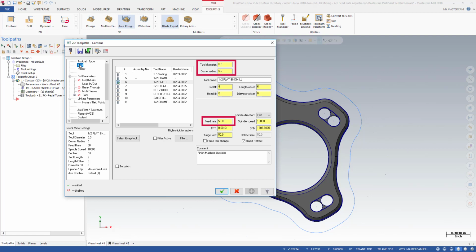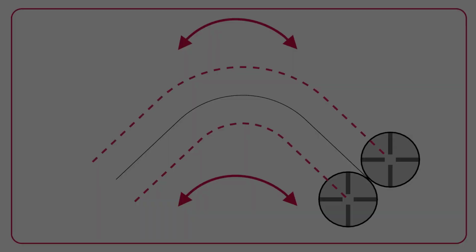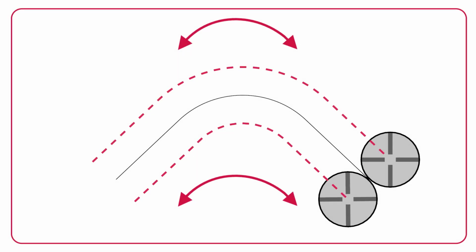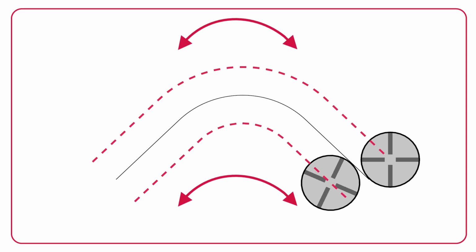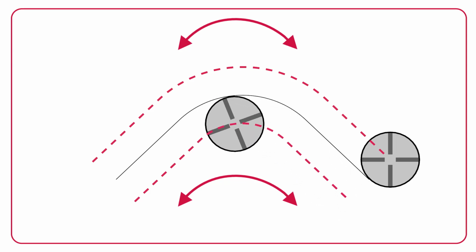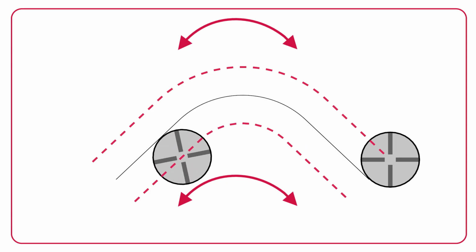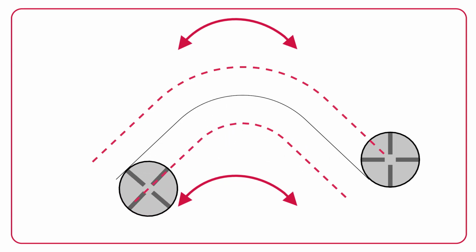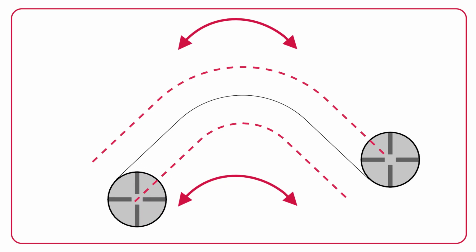Mastercam uses industry standard formulas to calculate the optimum feed rate for each arc move, factoring in the current motion's arc radius and cutter size. As the tool moves through relatively small inside arcs, the perimeter of the tool is moving through the material faster than the center of the tool. Now you can slow it down for safer and more efficient material removal.